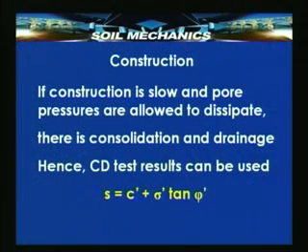On the other hand, the long term behavior, stability and safety of the earth dam is perhaps the most important aspect, and we have to ensure that the dam remains stable for the estimated or the design life of its span of performance. Let us take a look at what kind of shear strength test needs to be done and what shear strength parameters need to be used under these construction, drawdown and long term conditions.